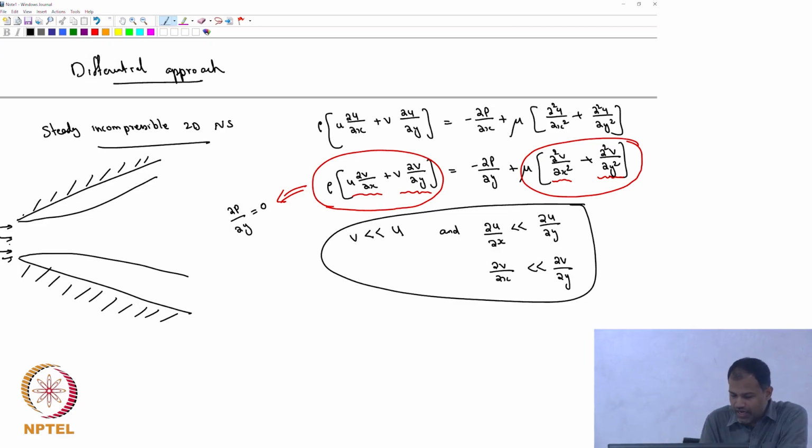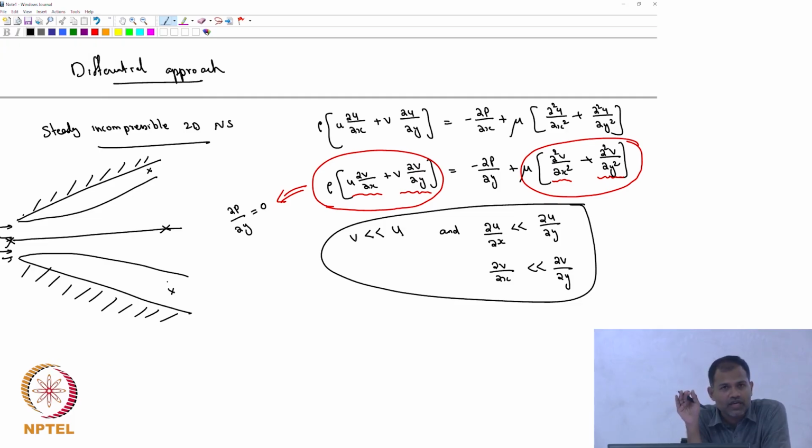So you can really apply Bernoulli's equation and calculate the pressure here and the pressure here. You can use the same pressure here also, because the pressure variation across the boundary layer is so small. The pressure variation along the boundary layer is then determined by what is happening outside. If pressure was changing with respect to y, then you would have to worry about how the pressure changes. But if you want to determine pressure inside the boundary layer, you can actually calculate it from the numbers outside.